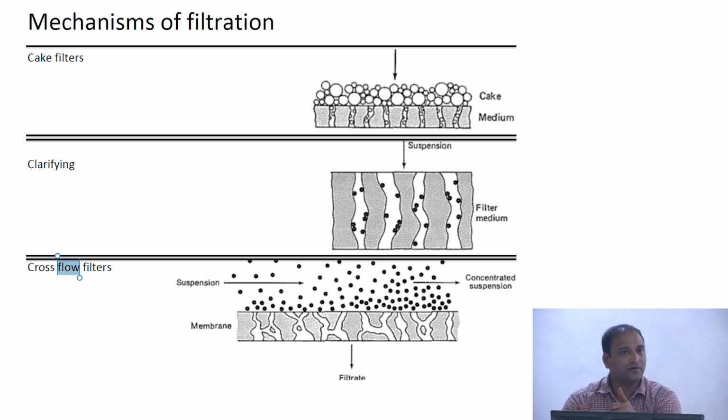However, in the case of the clarifying filters, the size of the pores is larger than the particle size, and typically the particles adhere to the surface of the medium because of some specific interaction between the particles and the medium that you're using.